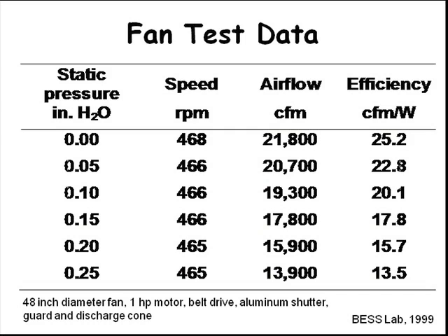Now, if you compare these efficiency numbers to the fan that Larry showed, the 24-inch, these numbers are much better. So it's common, for 48-inch or larger, that the larger diameter fans have greater efficiency. So it's not a good idea, though, to put in too big of a fan, because then you'll move more air and not do the job that you may want to do.